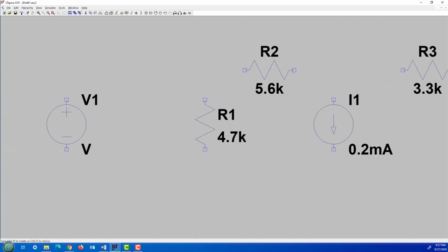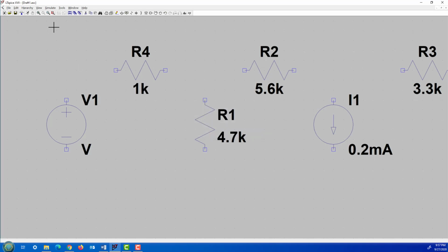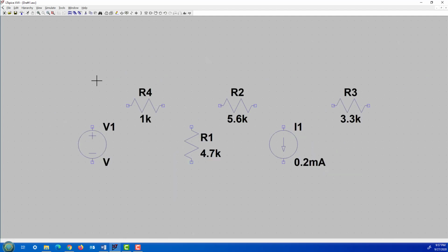You can just try out to see if that works. Like, for example, typing R does get your resistor. I just typed R, okay? Control R rotates it and puts it down. Okay, maybe I make this 1 kilo ohm, 1,000 ohm resistor, right? There we go. And then zoom out and maybe zoom out a little more, and that's how our circuit is kind of looking like. Voltage source V1, I don't know, make it 10 volts, right? 10 volt source.